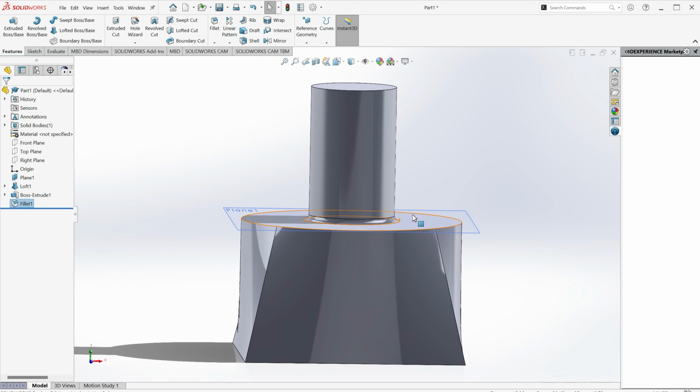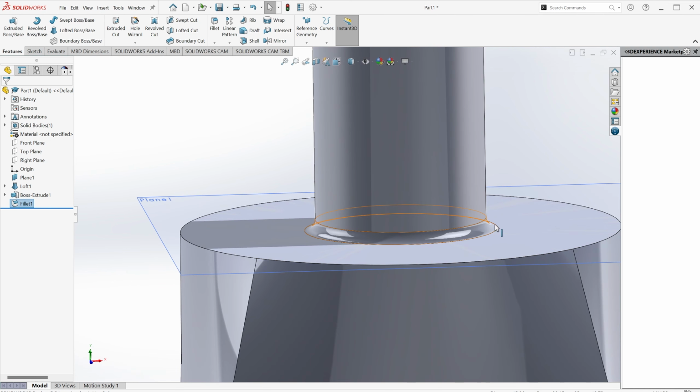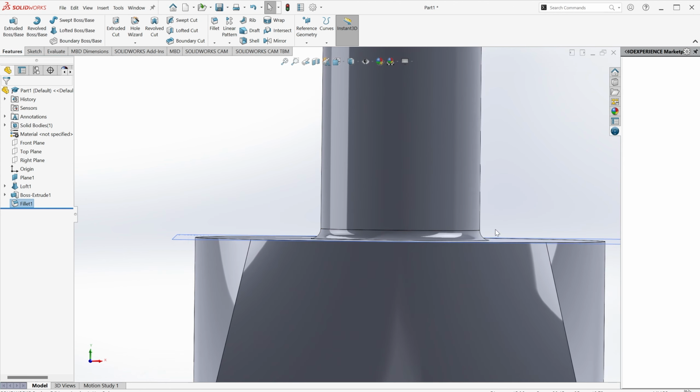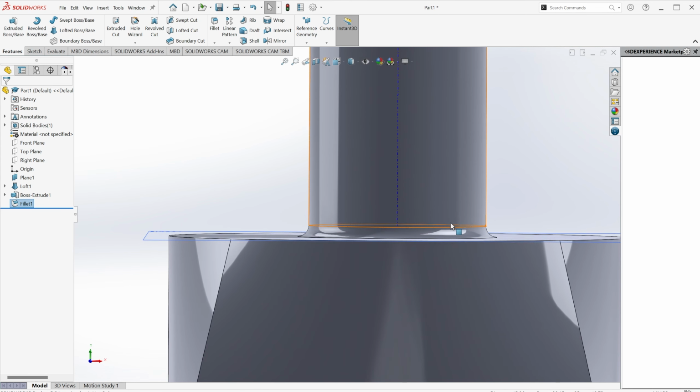Particularly if you're 3D printing this part and you're using an FDM type printer which prints in layers, this area here is an incredible focal point for failures. So putting a radius in here will improve that. Ultimately though, with an FDM kind of 3D print, this would still be a very high stress area, and with the layering that the 3D printer has created, still an area which is likely to fail.